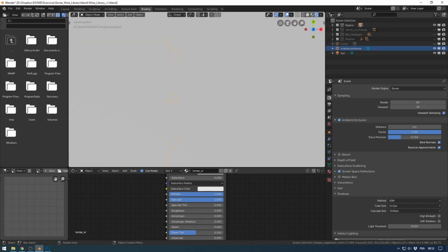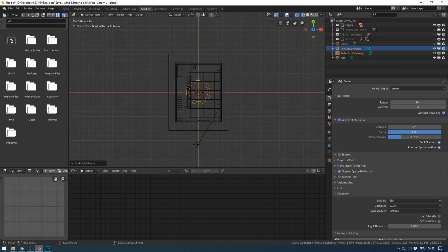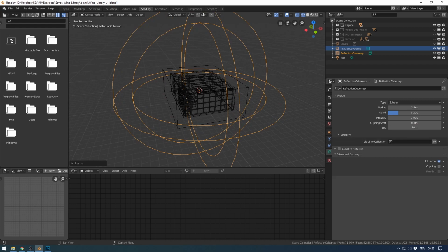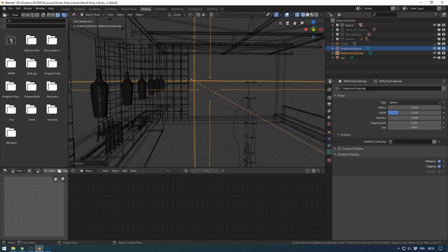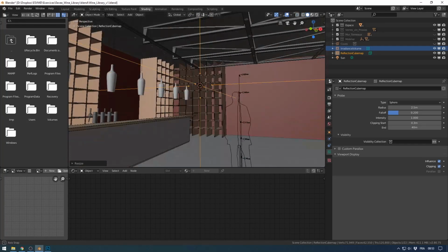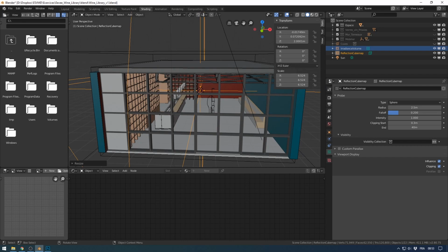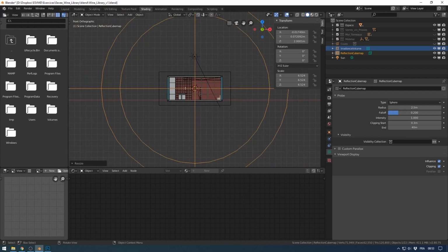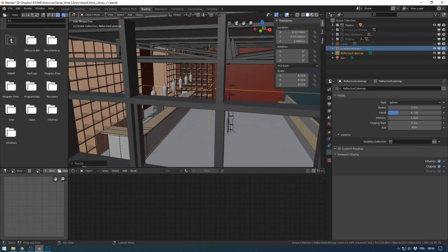And now I would like to add here a cube map, a reflection cube map. So I scale the reflection cube map, okay, and one important thing is to have the reflection cube map without any element here. Okay, it must be in an empty space, not inside an object or something like this. I'm not sure about how good it is to scale this kind of object, because normally it's not recommended to scale lights, cameras, etc. But I've seen a lot of tutorials with guys who scale this kind of object, and it works pretty well. So I use the same.